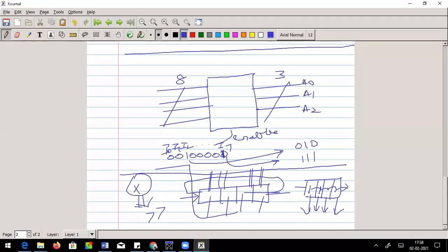I believe you have noted it. Say like this, I am having 0, 1, 1 and comma 0, 1. If I put them in the curly braces, you will get the output as 0, 1, 1, 0, 1. So what it means is, it will simply append the n bit with another m or n number of bits while you give a concatenation operation. So that's what we are stitching up here.